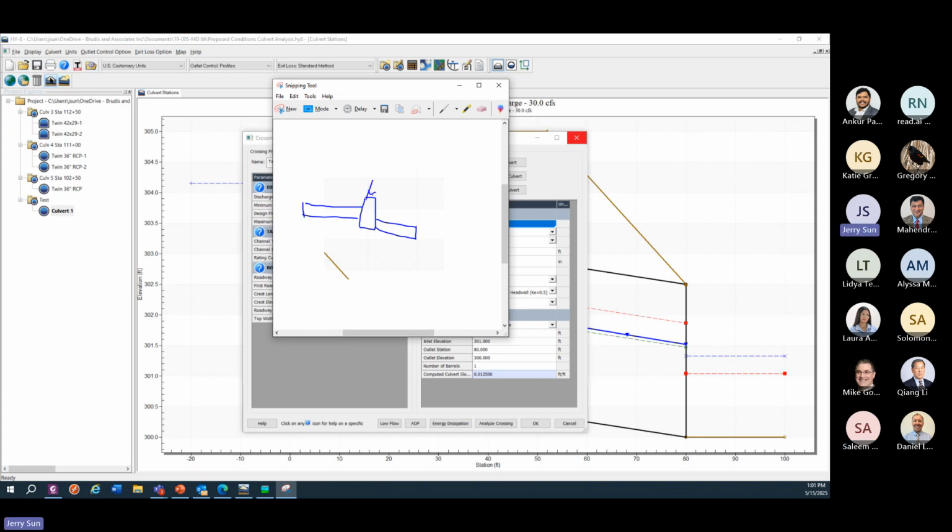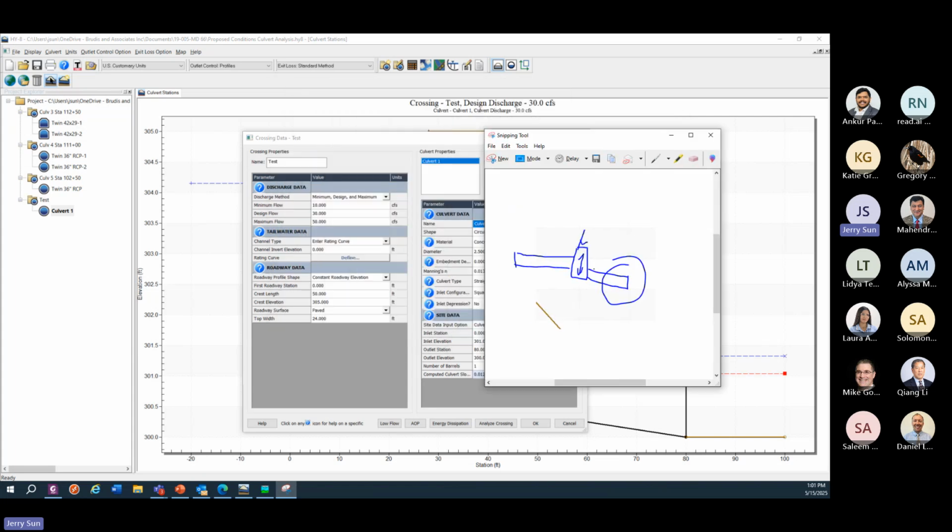Basically, if you have a large culvert but it has manholes, you design the rating curve first, then get the headwater with the flow. The headwater with the flow is the rating curve on the upstream culvert. Yeah, that's very good. You picked up a very good example, because the headwater of this HY analysis of the downstream culvert would be a tailwater rating for the upstream culvert. That's a design. Some people just don't care.